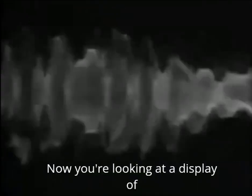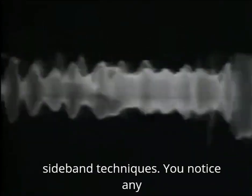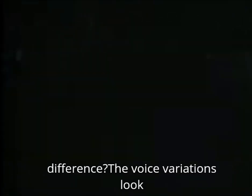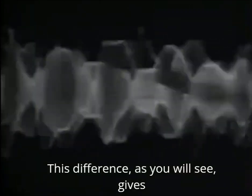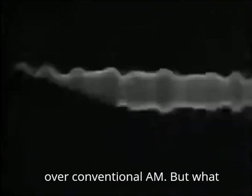Now you're looking at a display of amplitude modulation using single sideband techniques. You notice any difference? The voice variations look very much the same, but when we remove the modulation, or when I stop talking, there is no signal, no carrier. This difference, as you will see, gives single sideband a tremendous advantage over conventional AM. But what is single sideband?